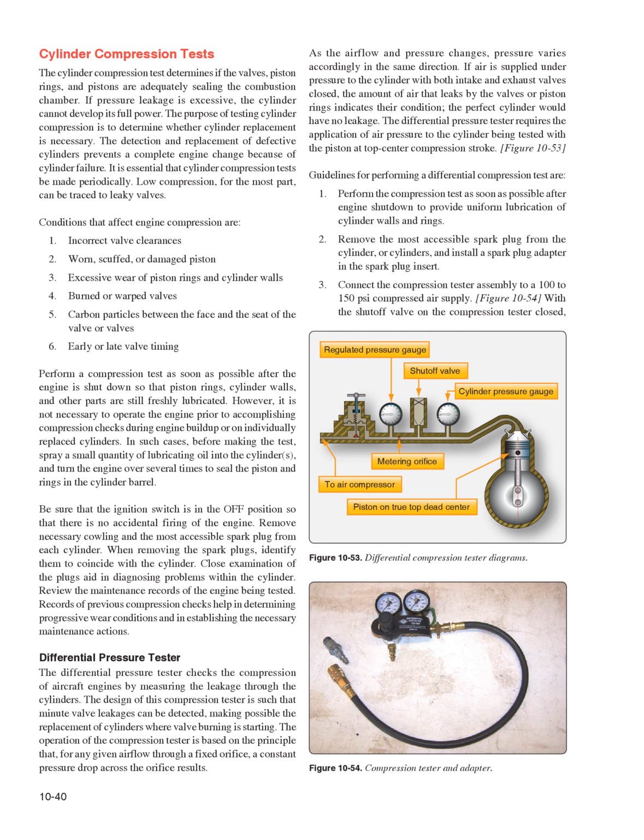When removing the spark plugs, identify them to coincide with the cylinder. Close examination of the plugs aids in diagnosing problems within the cylinder. Review the maintenance records of the engine being tested. Records of previous compression checks help in determining progressive wear conditions and in establishing the necessary maintenance actions.